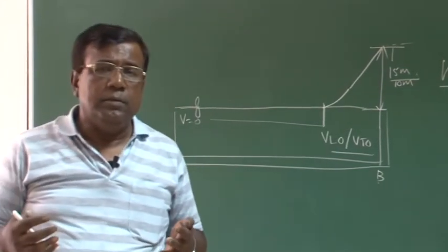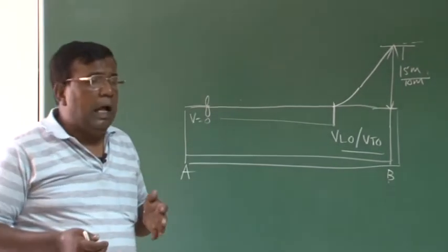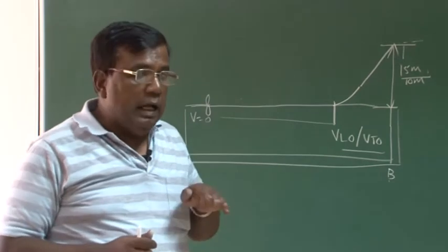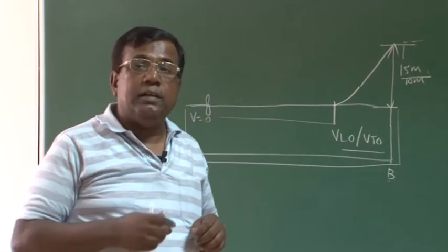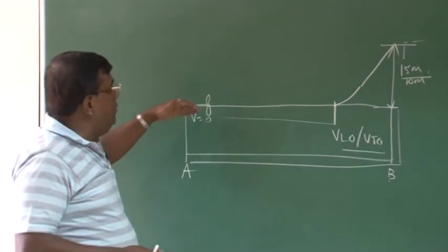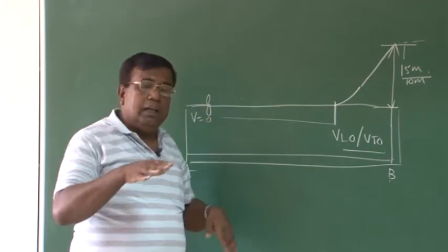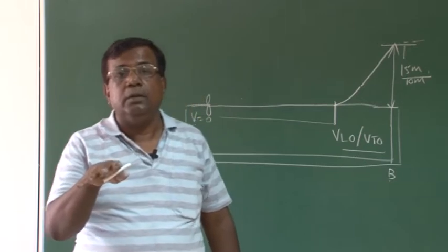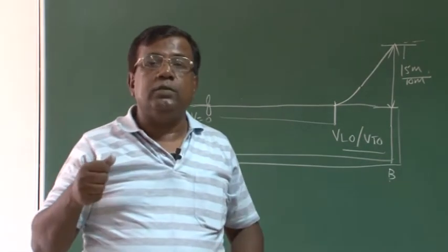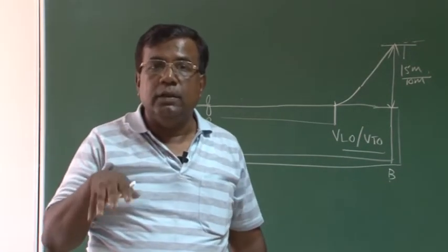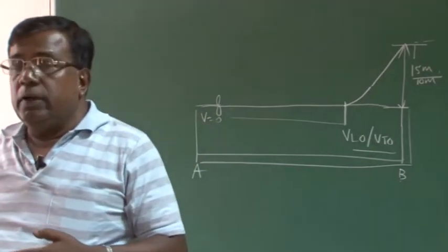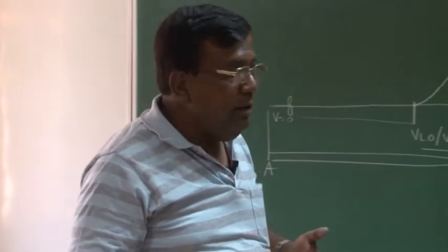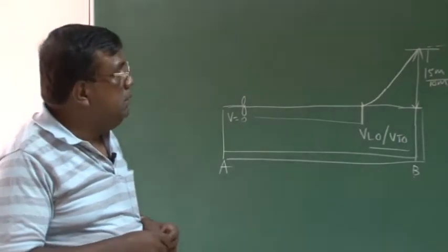For example, at what speed the elevators will be effective, at what speed the rudder will be effective. Imagine on the ground, I want to steer the nose wheel. I want to turn on the ground. How do I do that? I use the rudder and turn the nose. But for the rudder to be effective, there has to be some defined speed, so that the pilot should know.